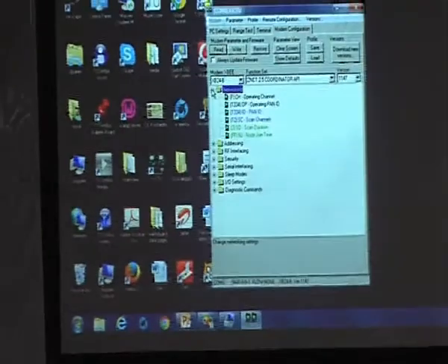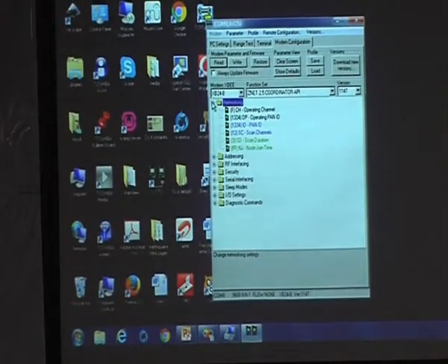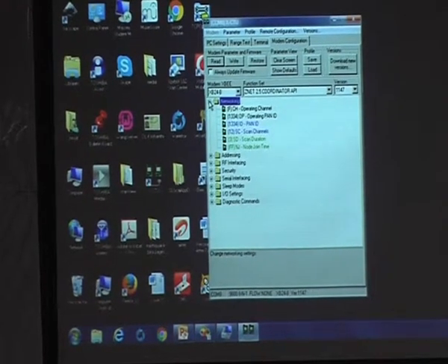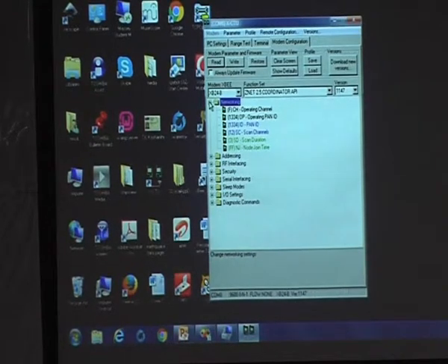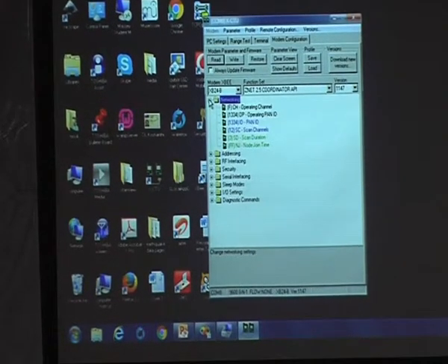So, here on the addressing you need to specify the destination; there is no need to specify the serial low and serial high. Serial low and serial high correspond to that particular radio communication module only. And if that radio communication module is trying to communicate with some other radio communication module, which you are going to call the destination, then that destination address high and destination address low should also be specified here.